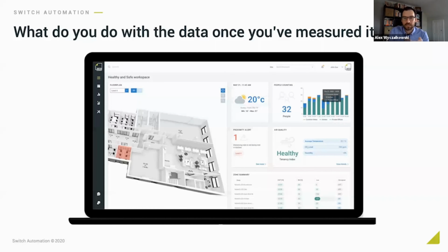One company makes a product that looks at temperature, humidity, CO2, and even VOC levels. So when you do a deep clean, you're going to have some of these volatile organic compounds come off, and you can actually sense that. So that's a sensor that can potentially validate, if you've got that data trended, you can validate the cleaning with that VOC spike. And at the same way, the building also has security access required.